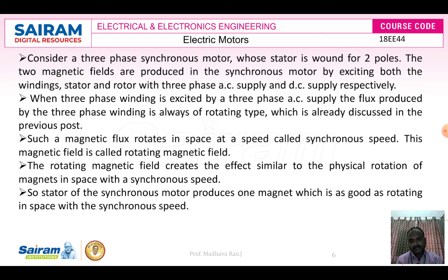The magnetic flux rotates in space at the synchronous speed. This magnetic field is called the rotating magnetic field, RMF, which creates an effect similar to physical rotation of the magnets in space at synchronous speed.